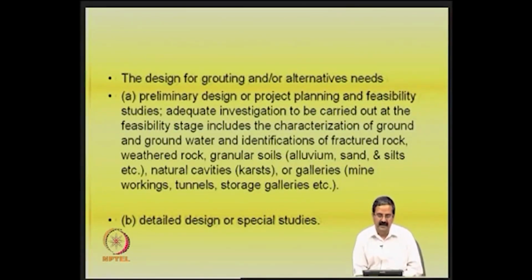When you are trying to design, you should look for certain things, particularly in the design of grouting. First is a preliminary design, in which you plan very well to see if things are feasible. So, you need to have adequate investigation right in the beginning, which includes characterization of ground and groundwater and identification of fractured rock.